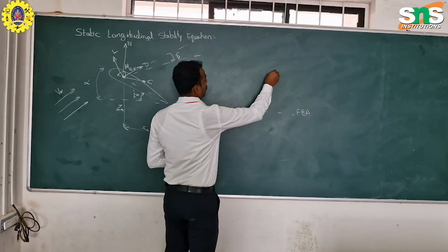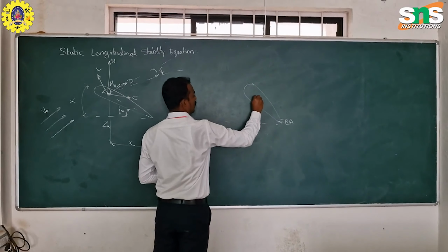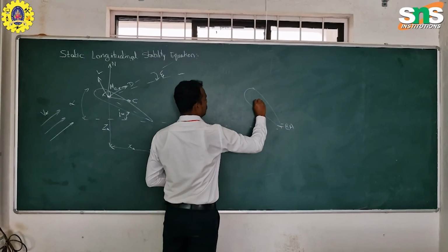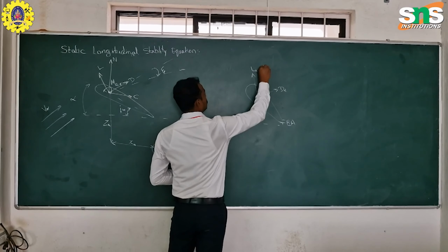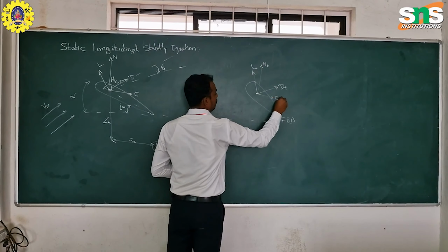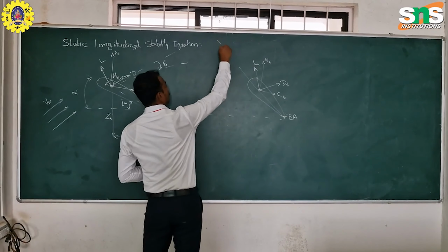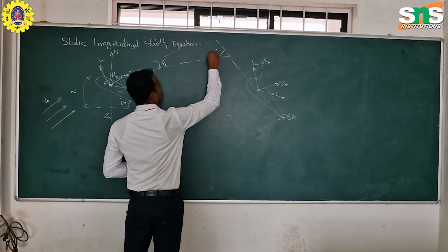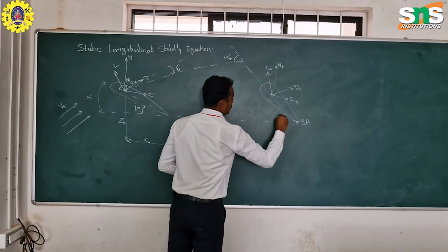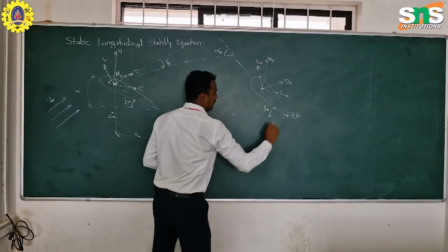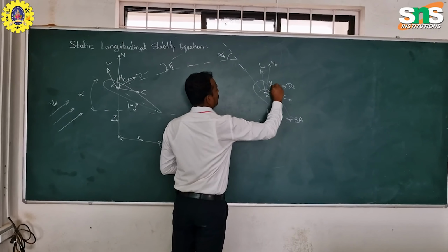Now we have to draw the tail section. Again, it has its own aerodynamic center. It will also produce drag of tail, lift of tail, normal force of tail and chordwise force of tail. We have an angle of attack, the alpha of tail, which is the angle of attack of the tail. The tail also has its incident angle i_t, and produces some moment about the tail.